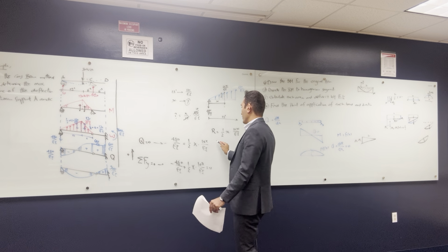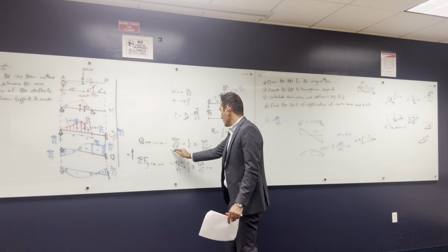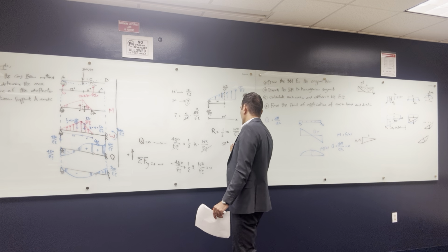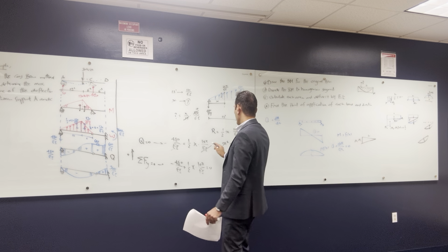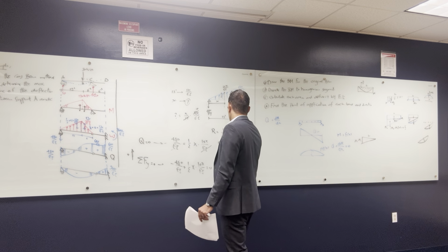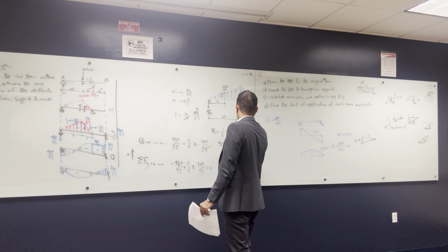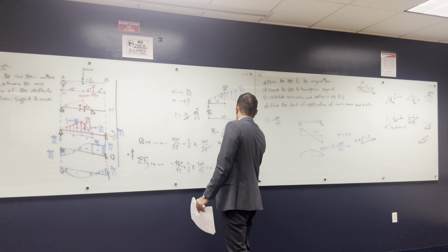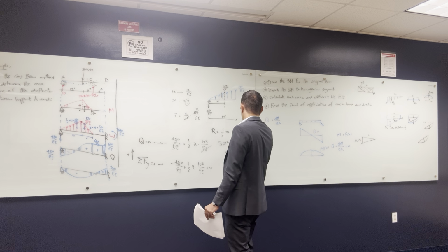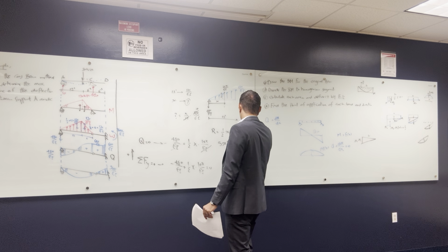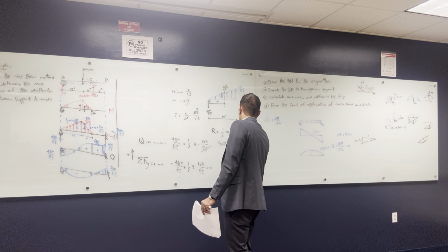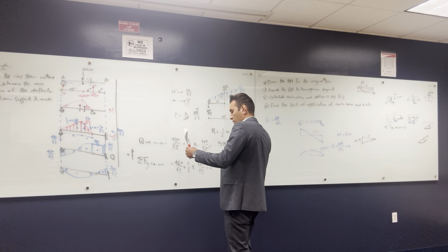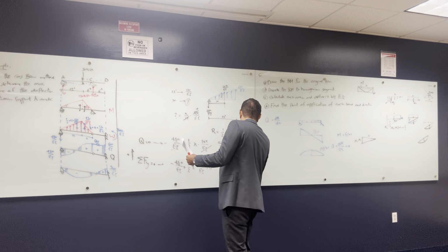You will find out after you solve this, you're going to cancel EI with EI, and you will find that X squared, actually, 1/2 multiplied by 10 is 5X squared, and this is equal 480. So you'll find that X squared is going to be equal to this divided by 5, which is 96. Then you take the root, so this is going to be 4.9 or something. No, 9.8 feet.